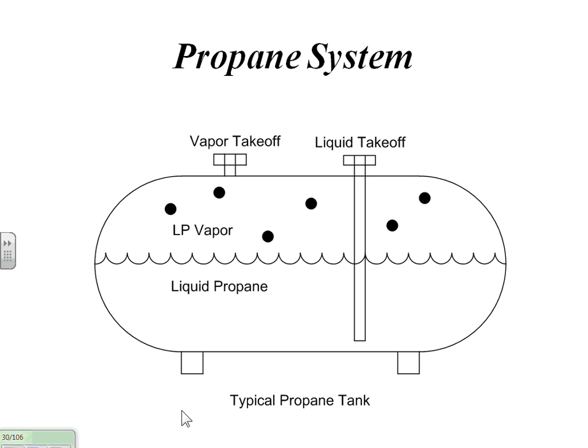They had the generator inside, and they said, this thing just won't run. And what happened was this tank shows the liquid propane down here. The ambient temperature was so cold that it couldn't vaporize enough fuel to run the engine generator.